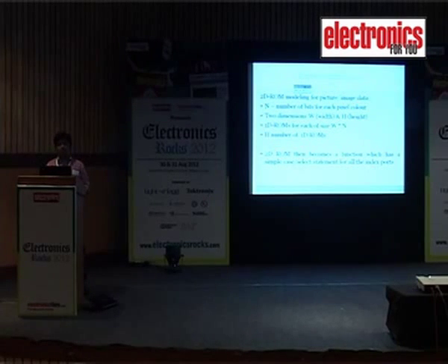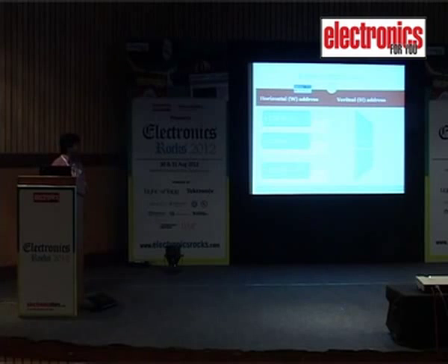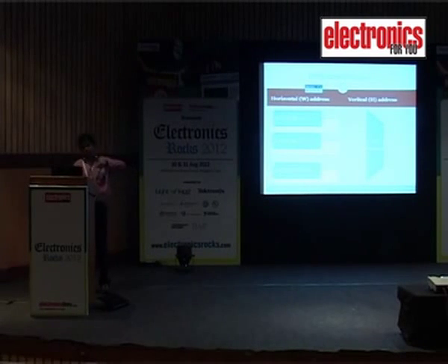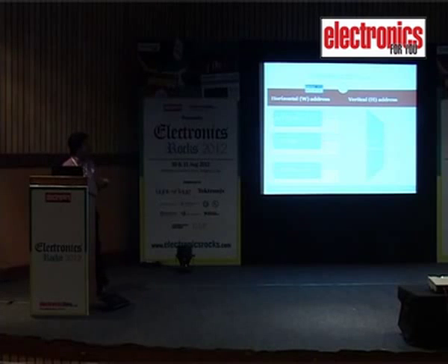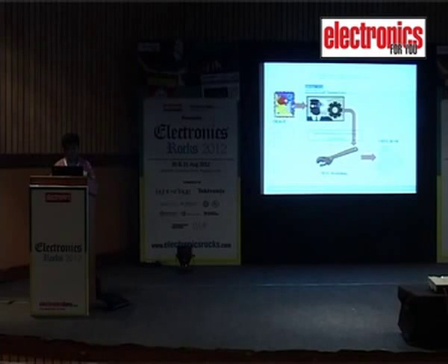This is what this slide simply means. This is a graphical representation. We have 1D ROM. ROM 0 represents the first read-only memory model. The last one is h minus 1, because counting from 0 we go from 0 to h minus 1. That will be h number of ROMs, and with the vertical address selection, we have 2D selection, where the output of this multiplexer is the final pixel output.